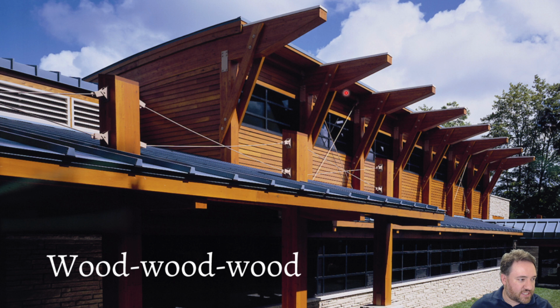Okay, here's another example of a wood-wood-wood connection. I'm talking about the connection up here or down here. Here we just have 2. We don't have a big problem in this case. The glulam member is going to shrink probably a bit less than the timber member.